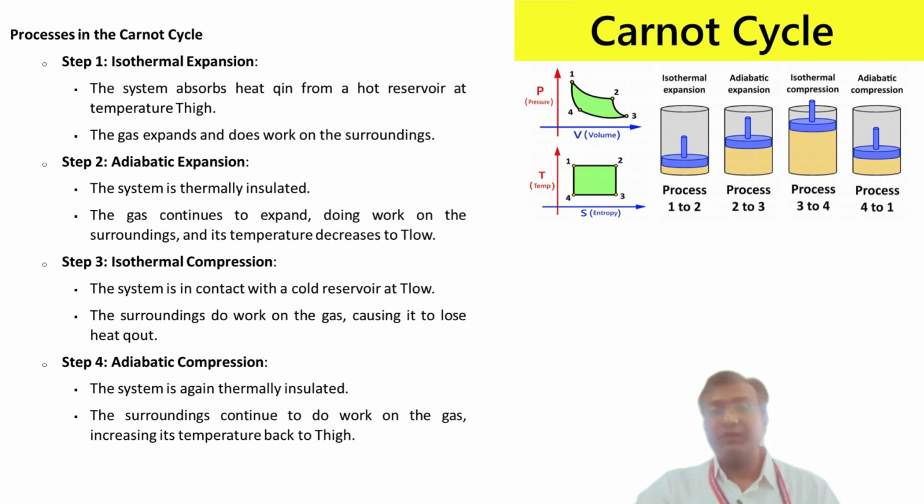Now, for now, it's important to visualize this process. If you imagine a pressure-volume PV diagram, the Carnot cycle forms a rectangular-like shape with two horizontal lines that are the isothermal processes, and the two steeper curved lines that are the adiabatic processes.